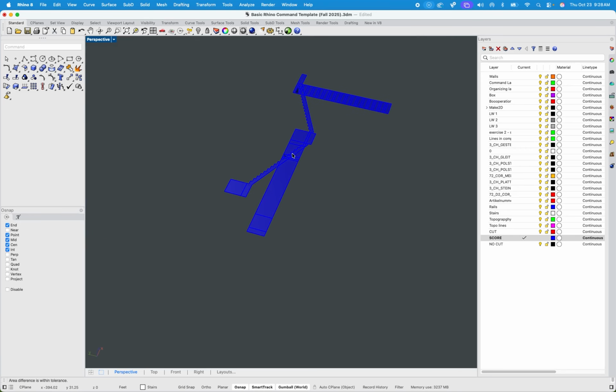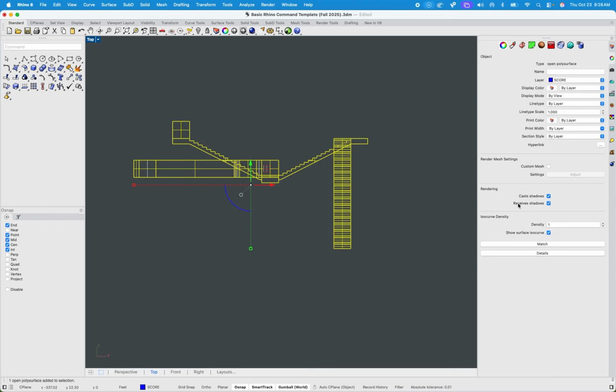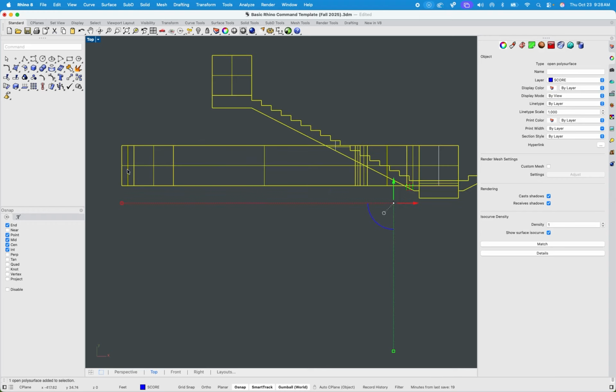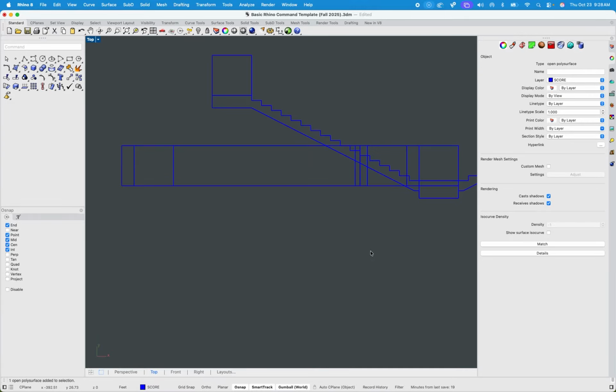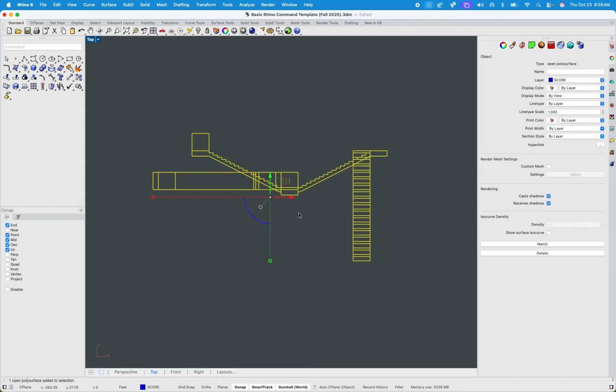Produces something, but let's take a closer look. Let me ask you, will that work on a laser cutter? Why not? They're all intersecting and overlapping. Thank you, guys. And in this case, if you ever get all these weird ISO curves, that's what those curves are called. They're basically all the midpoints of the object. You can also select the object itself and uncheck show ISO curve. I think it's easier to look at. Some people like the ISO curve there, and sometimes I do too.